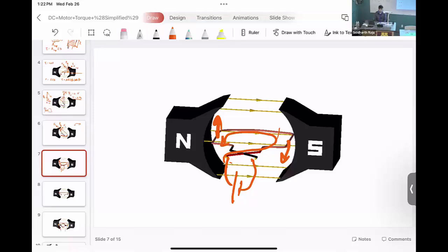Okay. We make the battery rotate somehow, or whatever the power source is, it would have to rotate as well. Fantastic. So let's say we put the battery on another motor and try to spin that motor. That motor would still have the same problem, right? How do you rotate the rotor of that motor? How do you energize that rotor? Okay, you use a slip ring or brushes. So we use a slip ring or a commutator.